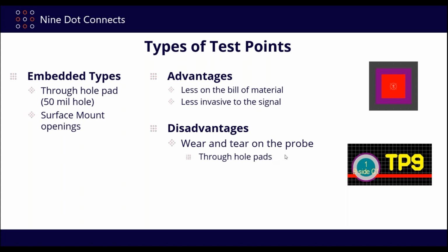There's going to be obviously wear and tear on the probe. So if you do stick it in the hole and you don't have that probe mount, there's a chance that you're going to damage that particular probe tip. So just be aware of that. And then there's the hassles of holding the probe. The joke always goes, the good Lord gave us 2 hands, but on the test floor, about 4 or 5 hands would be more necessary.